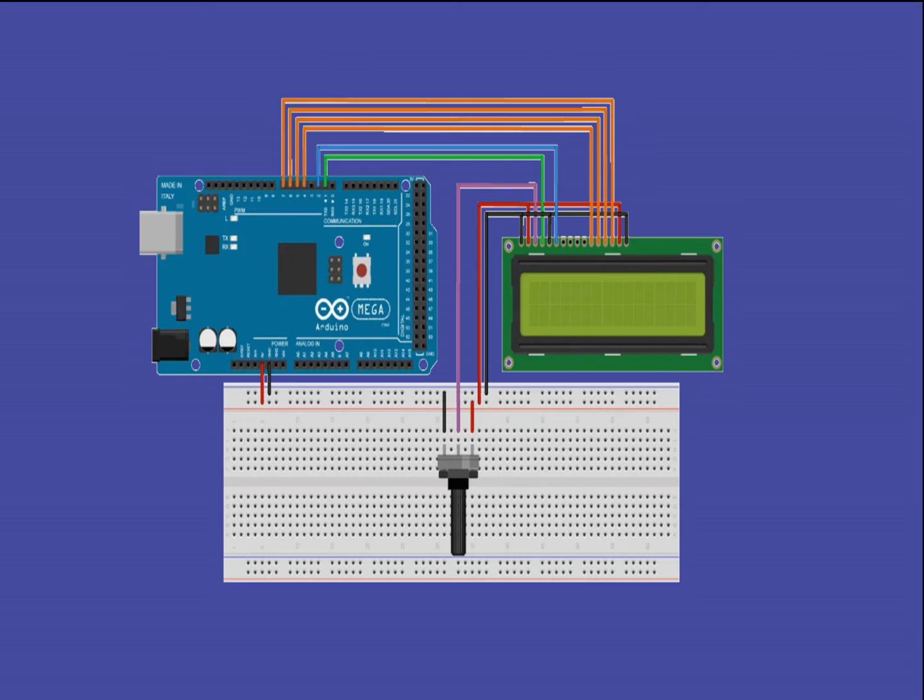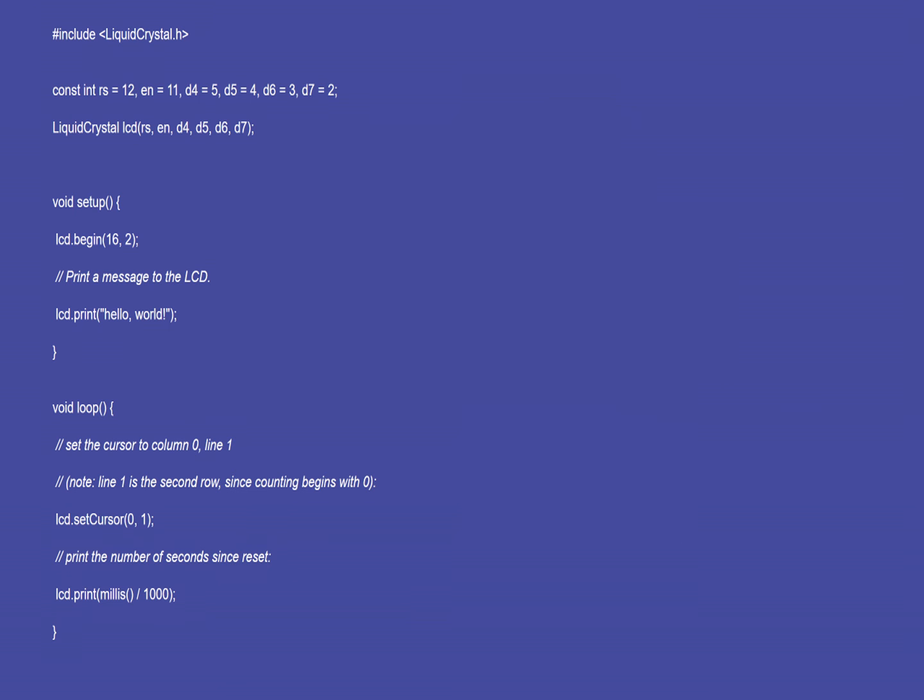You may ask if you can use the LCD without a potentiometer. Well, in case you don't have a potentiometer, it is possible. You can still adjust the LCD contrast by using a voltage divider made out of two resistors. Using the voltage divider, we need to set the voltage value between 0 and 5 volts in order to get a good contrast on the display. But this is not the recommended approach and is certainly more complicated than using a potentiometer. So, I would not advise you to adopt it. The potentiometer is all you need to control resistance.